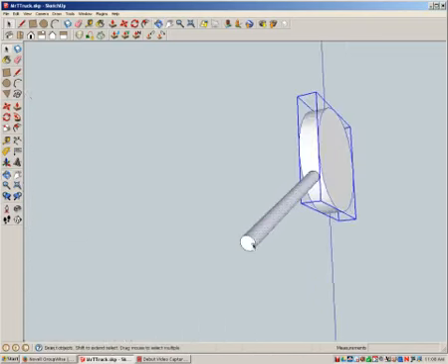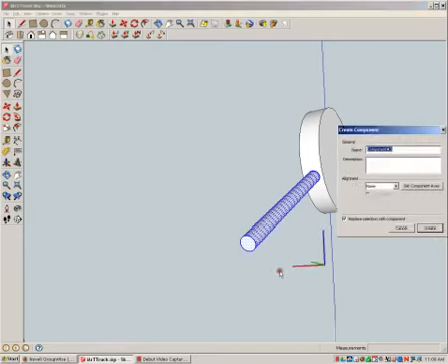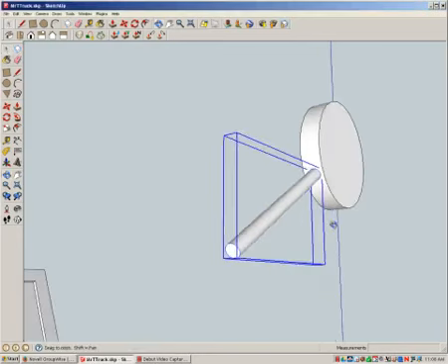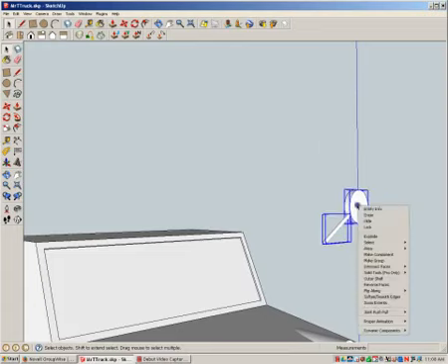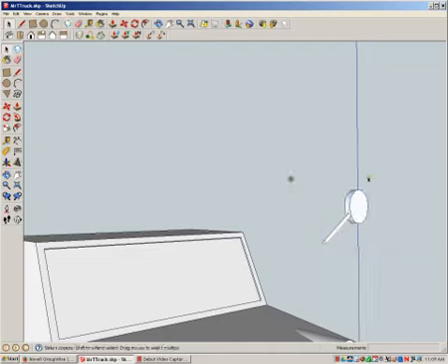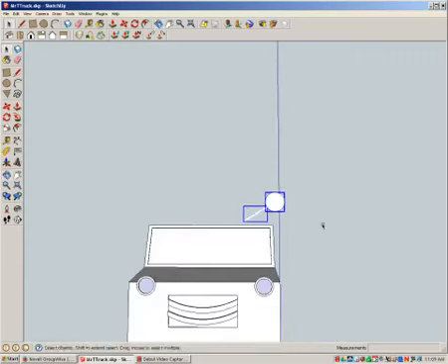It did not. So we're going to have to triple click on this. We can make this a component too, or we could just triple click on it. We could also select all the parts and make that a component, and then it would be one piece. Or we can just hold the Control, select them both, and we can start moving.